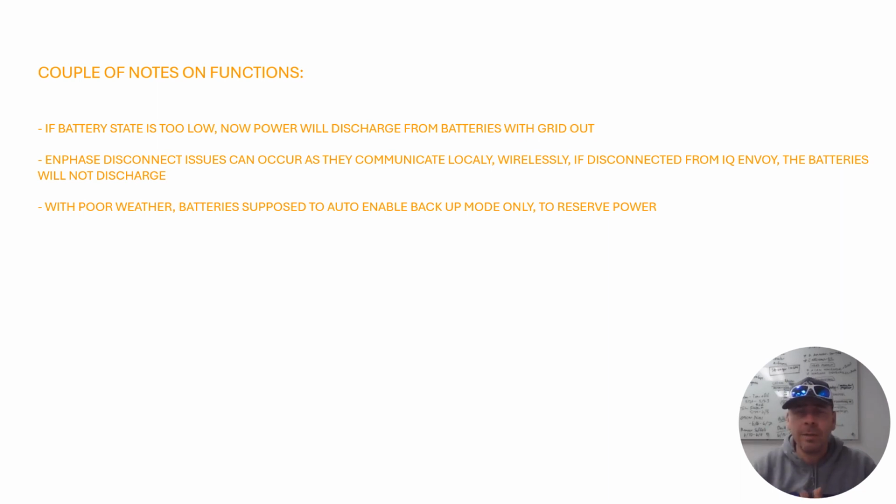I rarely see any of that with NeoVolta, but it does happen. I know LG had some major issues with their batteries with the SolarEdge system when they were launching those a few years ago. But it's a normal problem, and due to safety concerns it's built into the programming to not work if there's a lapse in communication. So if you see that, don't be too alarmed.